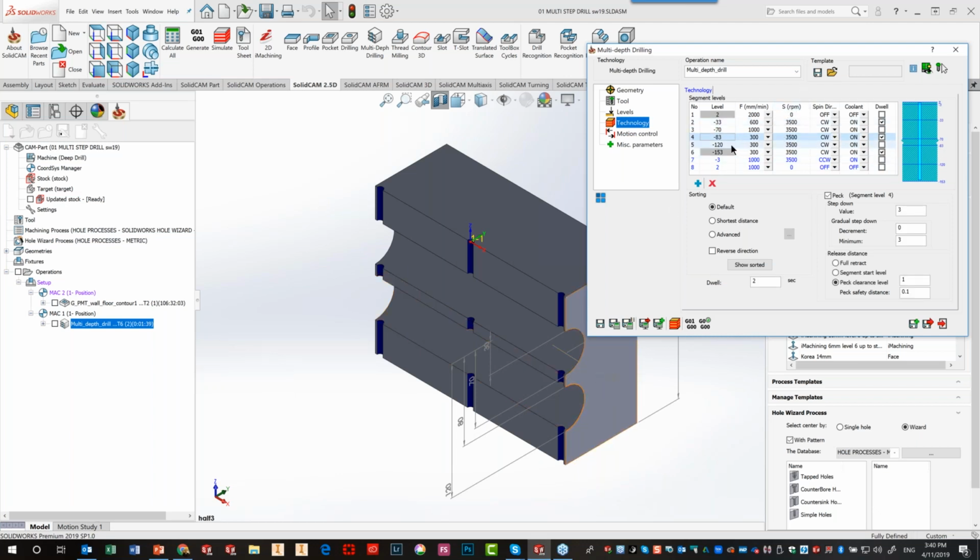Same thing I did in the first segment, number 5, going all the way down to 120, up until this point over here, and then going down to 153, again having my PEC on, okay? And then when I went back up, just to show you I can do it, I went up to minus 3 millimeters, and I decided to go counterclockwise for whatever reason I may want. And then when I went from 3 back to 2, I decided I don't need a spin at this point. Now, this sometimes is very, very helpful.